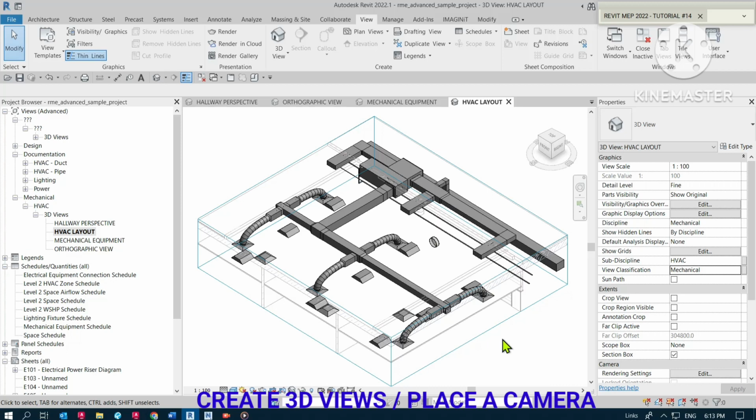What you want to see in the view, placing the camera too close to the model creates several angles that may be unrealistic or may not reveal the perspective view. If you place the camera further away, it will be easier to adjust the view.